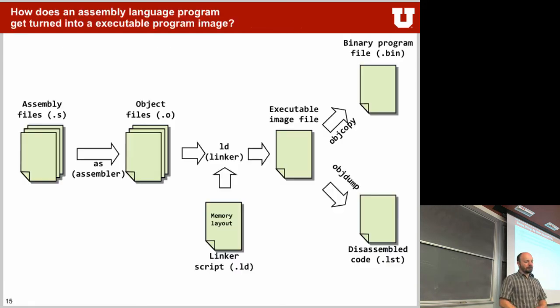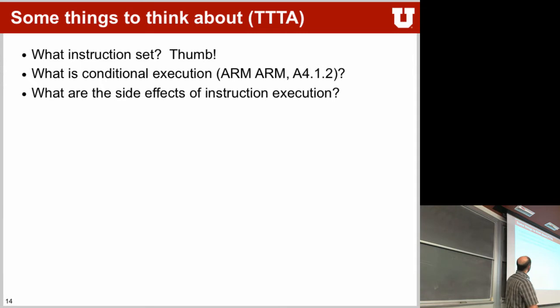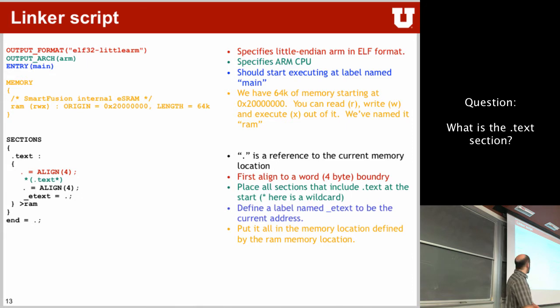All right. Excuse me. Yes? In slide number 14, what's the meaning of .text? .text means that the text section of your object will be put into this memory location. Right? And in the text section, you basically have all the operation codes. Like your application is sitting in the text section of your object. So it will get all of these sections and they will be put into this particular memory location.